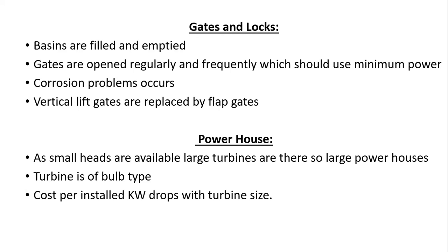So a gate will transfer the hydraulic load to the concrete structures in present conditions. If the operation is to be rapid, meaning continuous, and it is operated rapidly, this is efficient. It should also be ensured that gates can open under the maximum differential head. This has the great advantage of making the tidal basin face of the gates as flat as possible. So these flat gates allow flow in the direction of sea to basin.